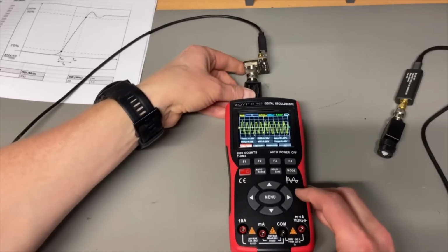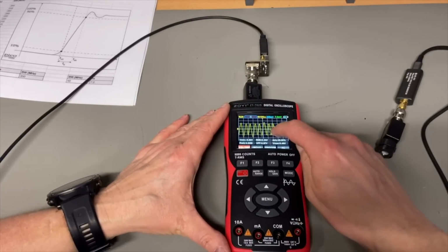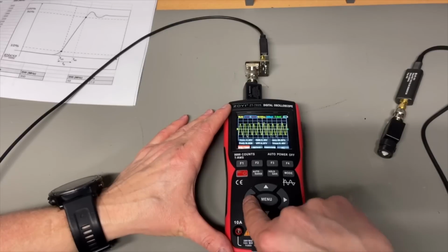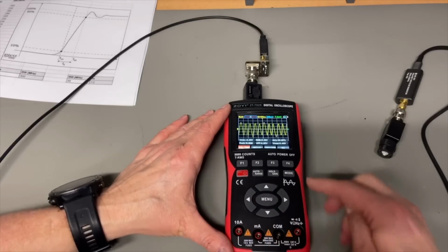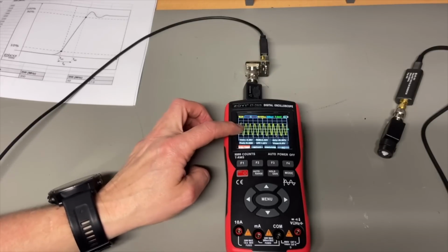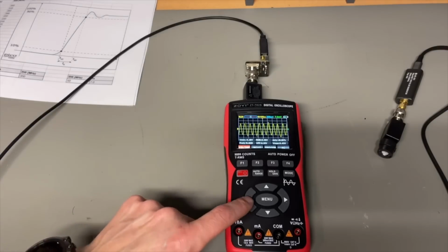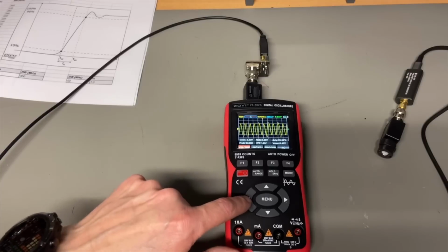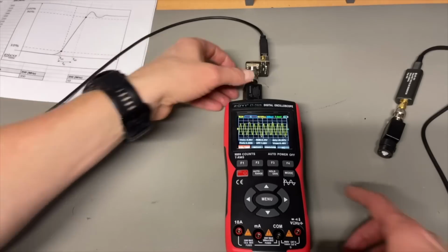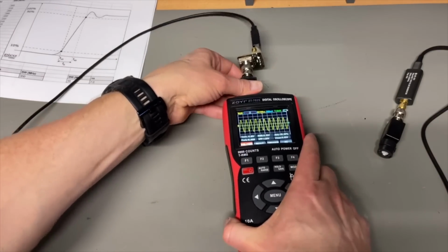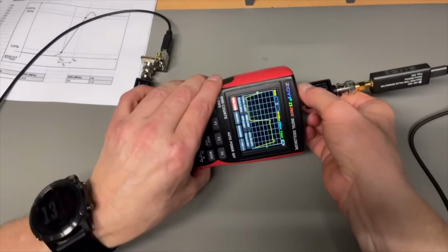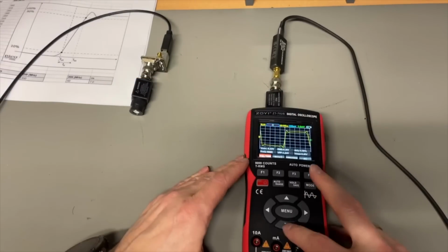And well, we see already one thing, it does show, and maybe it's within the 70%, but this is another practical problem that the time base cannot zoom in. So maybe it did the 70%, we didn't test, but it is useless because of the time base. The rise time now also makes no sense because we cannot zoom in that fast. But let's go to 1 megahertz. That would be easier to see. So at least we can then determine.